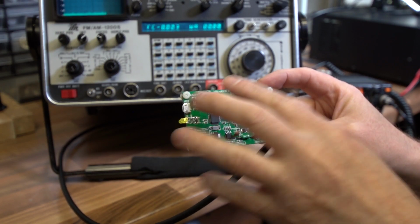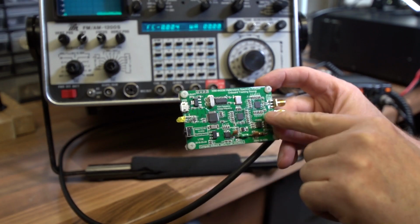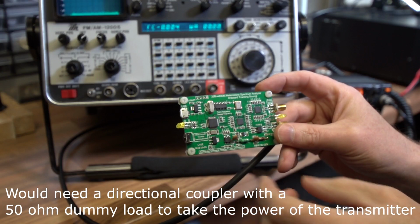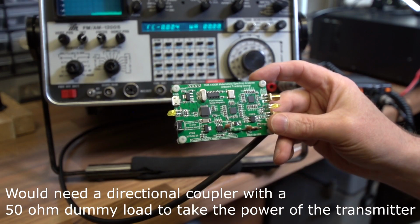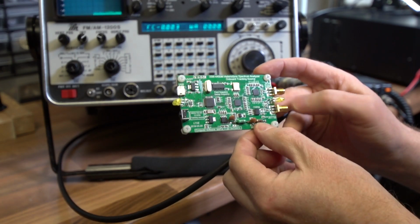You couldn't plug anything like this directly into a radio. It would just blow it up straight away, because you'd have too much power coming in. So you'd have to use it with a directional coupler and a dummy load, something of that nature, to sample the RF safely before you inject it into the spectrum analyzer input here through the connector there.